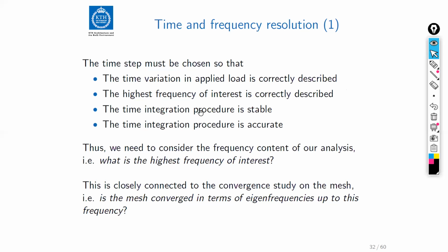So we need to know that the highest frequency that we want to include is correctly described, but we also need to think that we might have a wider frequency band than we expected. And then, of course, if we're doing time integration, the time step must also be chosen so that we can ensure that the integration procedure is stable. And I guess it goes without saying that we also need to assure that it's accurate. Now I said it anyway, but of course this is important.